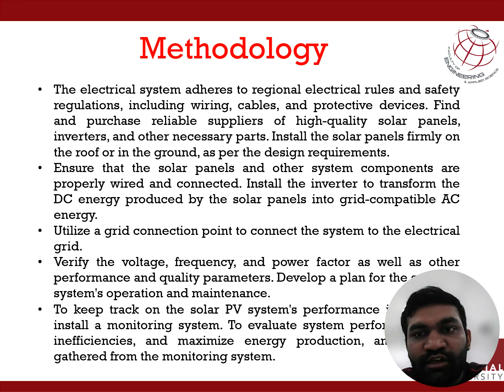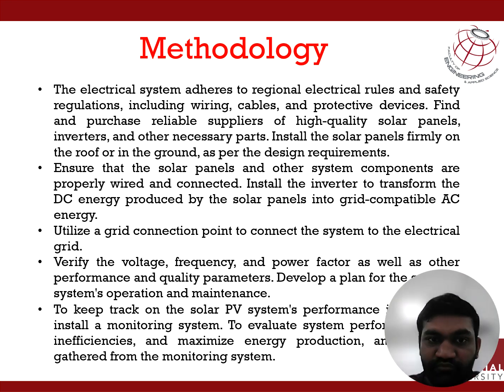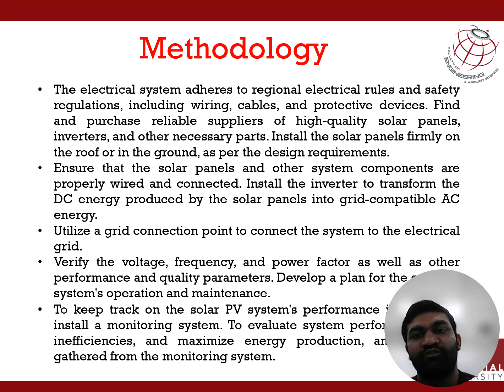Install the inverter to transform the DC energy produced by the solar panels into grid compatible AC energy. Utilize a grid connection point to connect the system to the electrical grid, and after that verify the different parameters like voltage, frequency, power factor, as well as other performance and quality parameters, so we can get accurate input and output. Develop a plan for the system's operation and maintenance.